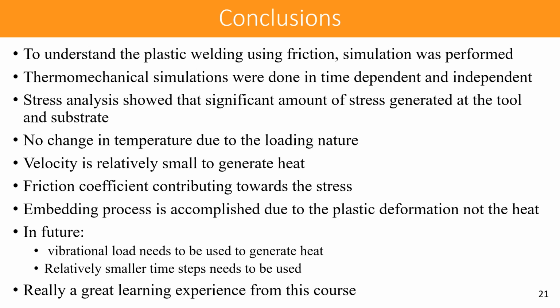So at the end of this presentation, I would like to mention several things. One is that to understand plastic welding using friction at the interface, a simulation was performed. Thermomechanical simulations were done time dependent and time independent as well, just to compare the results and see the effect of time dependency.